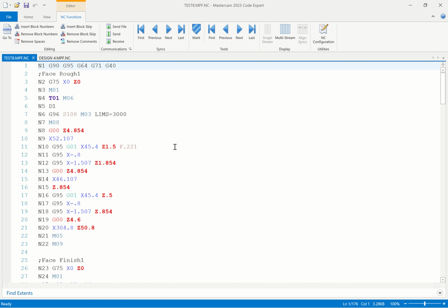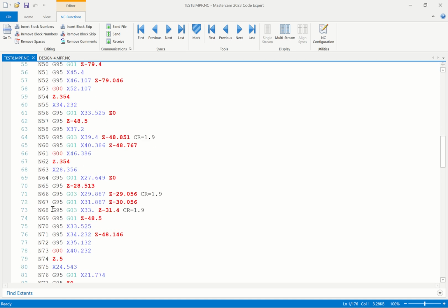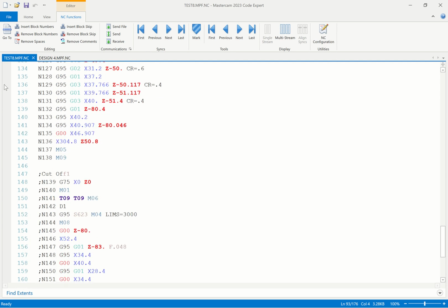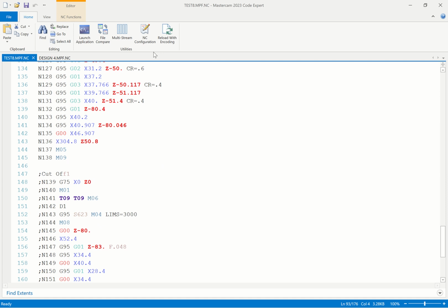See, this program is now for a Siemens machine. This is another program for a Siemens machine. For this machine, it uses T and D, that is tool number and tool offset, and you see the program is very simplified. This is the program. You are also able to do backplot using these editors. So this is the Mastercam editor that we have used.